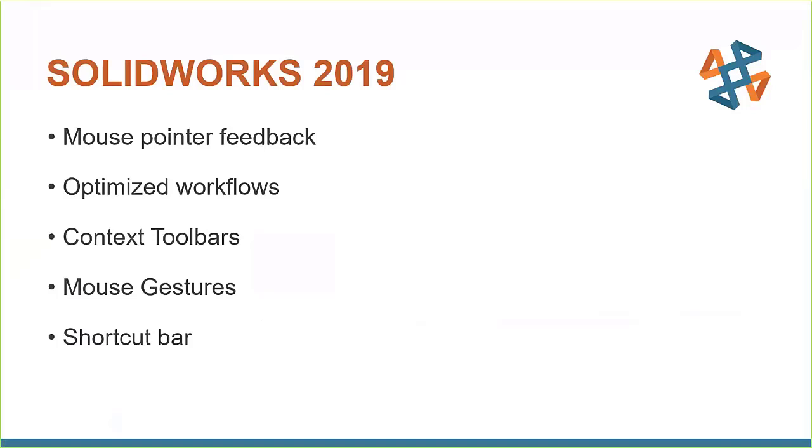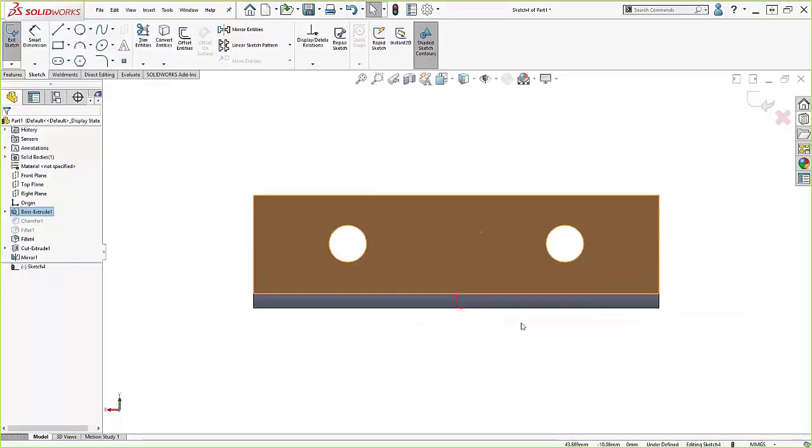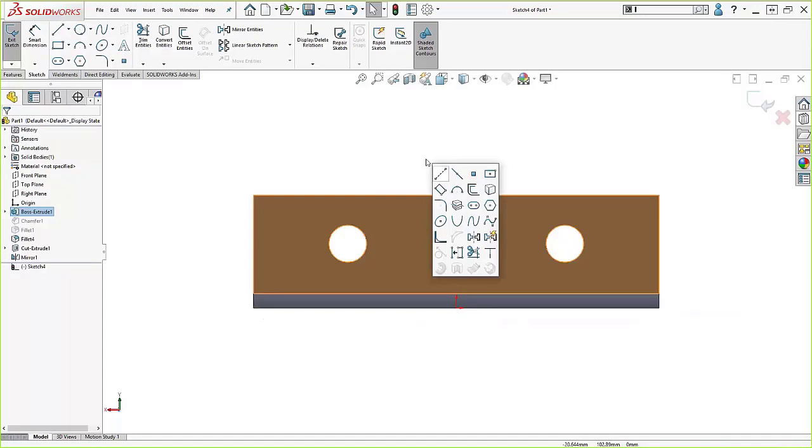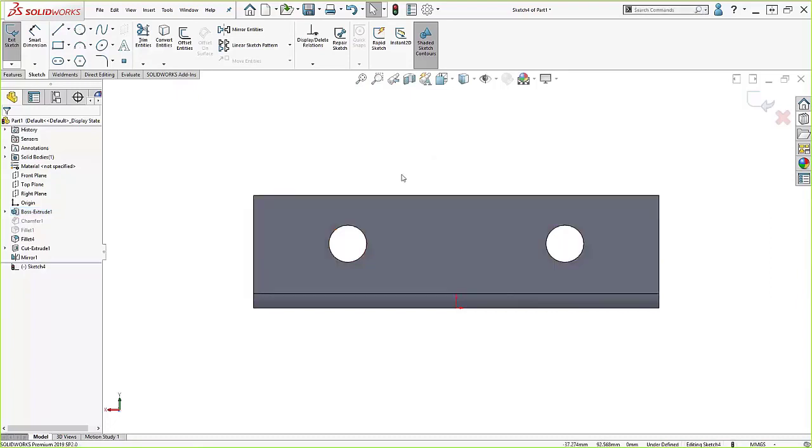and this is the shortcut bar. Okay? The shortcut bar is used using a shortcut key, and we'll talk about those also. But if you use the S key with the shortcut bar, this is what happens when you're in a sketch. When you're in a sketch, you get all these tools. Right now, most of them are sketch tools, but you'll see down at the bottom, these are actually features that I've added to this. This is all fully customizable. Most of these things are fully customizable for you, and we're going to show you how to do that as we move on later down in the presentation.